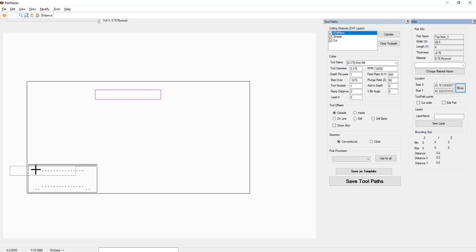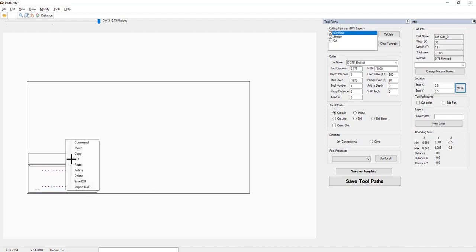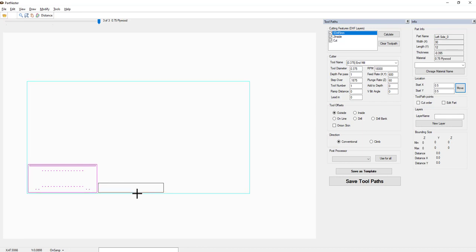move, and then selecting in the upper right quadrant of this part, it will place that directly on top of that part. If I wanted to place this part to the right, we would right-click, select Move. In the lower right quadrant of the part, click, and it gets placed diagonally. Move it and right click in the upper right. It gets placed to the right of that part.